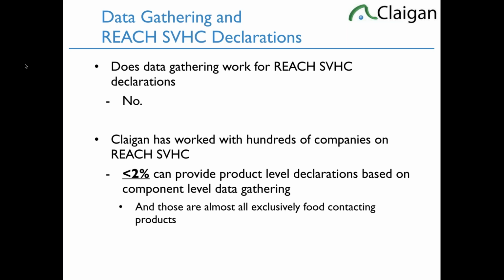Our favorite, and probably the biggest recall problem in Canada right now for all products, are twist ties. You buy a power cord, awesome. It's got a twist tie on it. They're like, oh, what's a twist tie? Plastic. It's actually flexible PVC that uses phthalates and short chain chlorinated paraffins. The SCCPs are banned in Europe and Canada and are a recall problem. And the twist tie for the power cord that you buy separately is not even on the BOM. So we're not a huge fan of it.